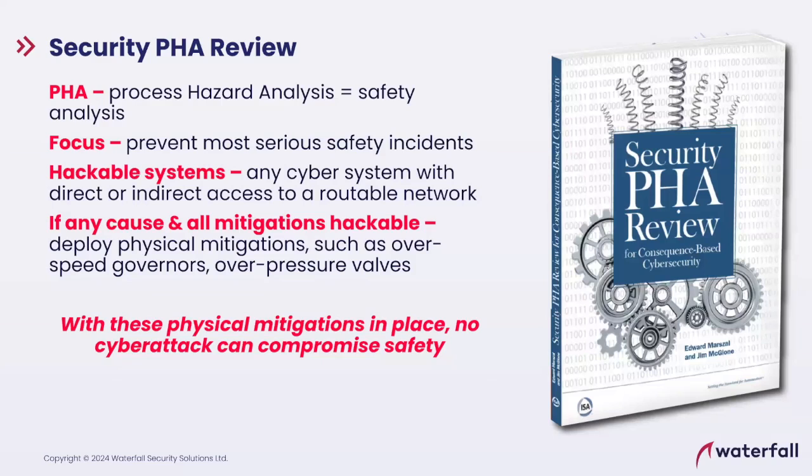And what they say is, look, you're required in most places, you're required by law. In North America, it's OSHA, the Occupational Safety and Health Administration. In other countries, it's other administrations. But in a lot of places you're required by law: if you have a dangerous physical process, you have to do a safety assessment every couple of years. The output of that safety assessment is often a spreadsheet. There's a row for each unsafe outcome that we need to avoid. We need to avoid the boiler exploding.